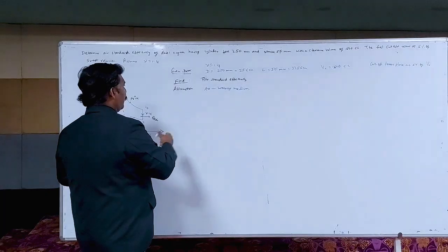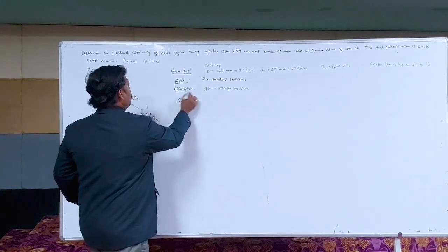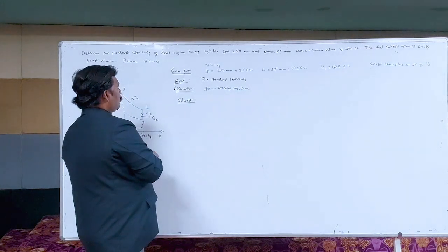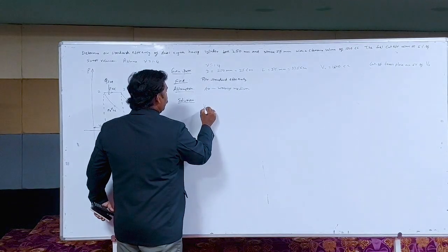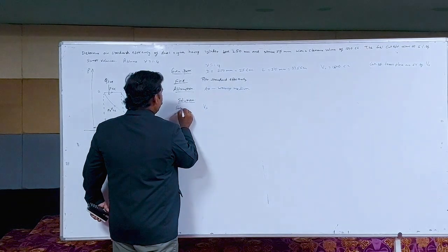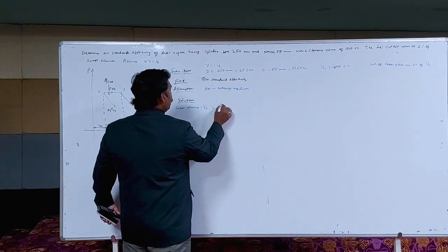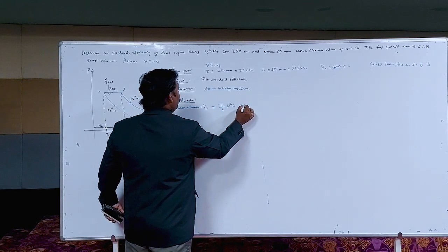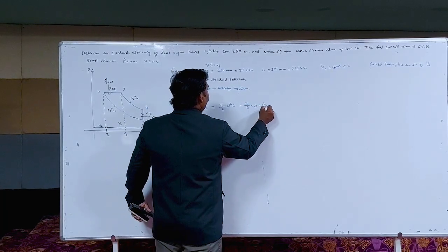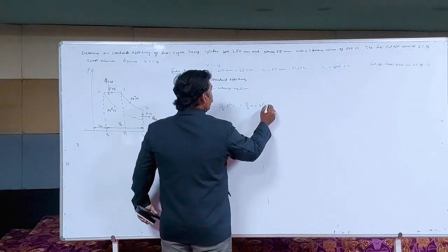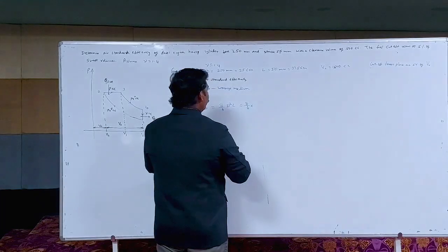Now we will start giving the solution for the given problem. So first try to find out what is Vs, swept volume. Swept volume, Vs is equal to pi by 4 d square L, that is equal to pi divided by 4 into 25 square into 37.5 in terms of centimeter.